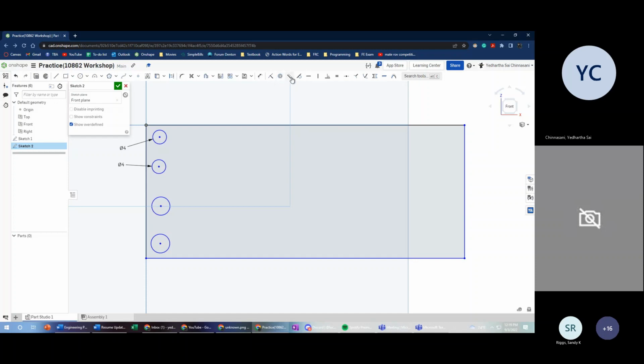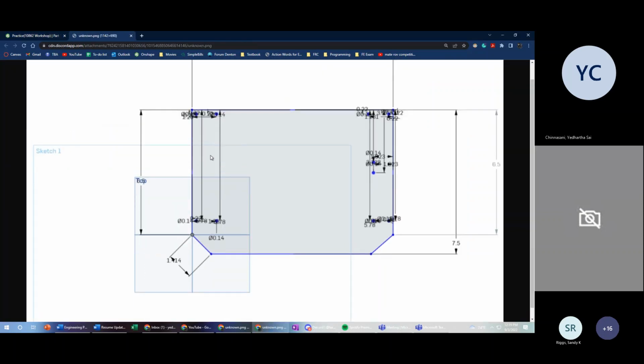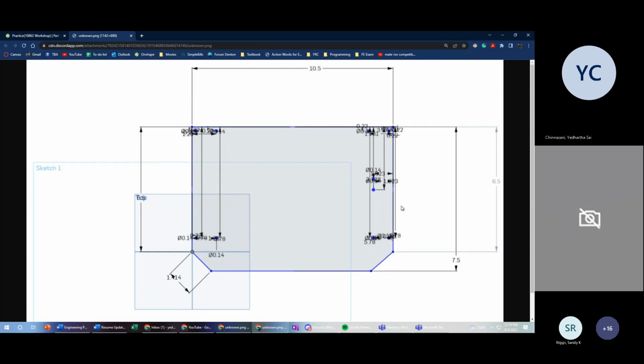It should be your favorite options whenever you're using sketching. Coincident, concentric, parallel, tangential, horizontal, vertical, perpendicular, equal, and midpoint. These tools I use basically in every sketch I make, because whenever you don't use these tools, you have a mess, right? Like this is a mess, so you can't see what the number is, and you can't see anything, right?